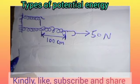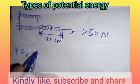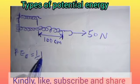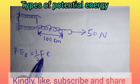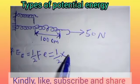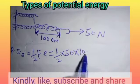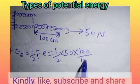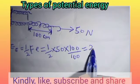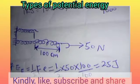So elastic potential energy will be given by half multiplied by the force multiplied by the extension. Then you substitute, which is equal to half, our force which was applied is 50 newtons, multiplied by extension. Ensure that the extension is in meters. So you have 100, you divide by 100 to convert it into meters. So you have 50 divided by 2, which will give you 25 joules. So that is the elastic potential energy.